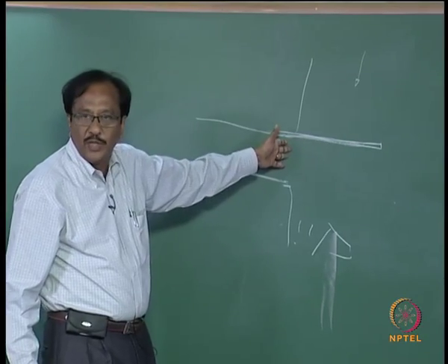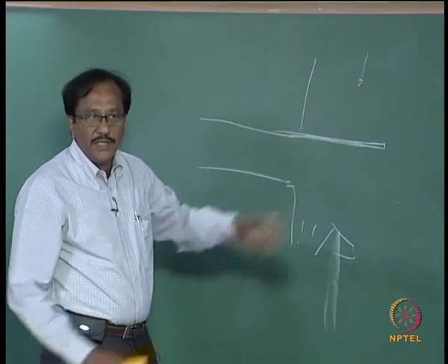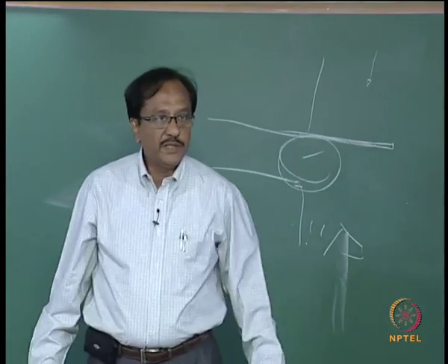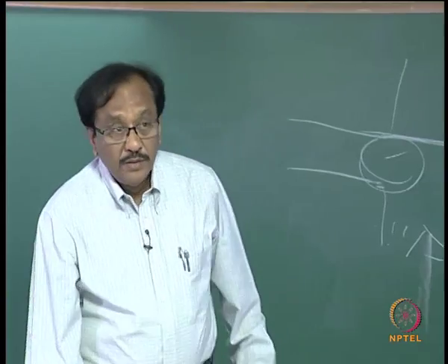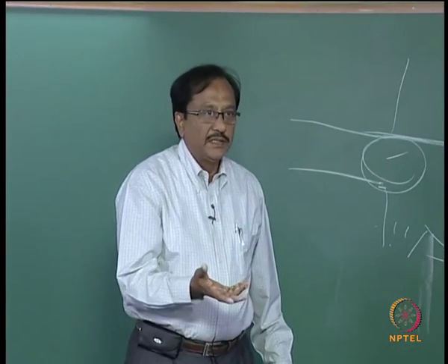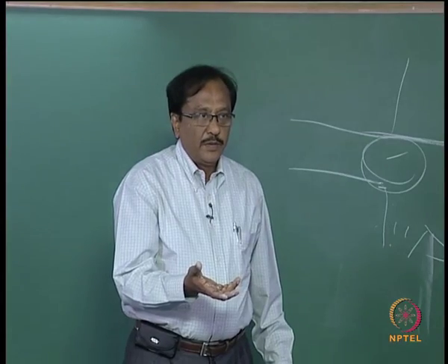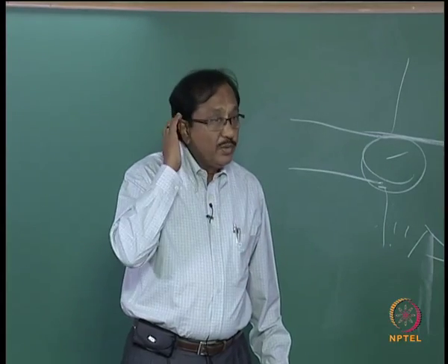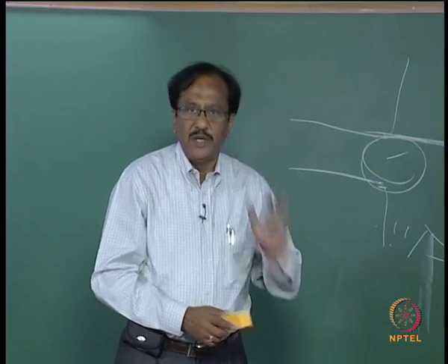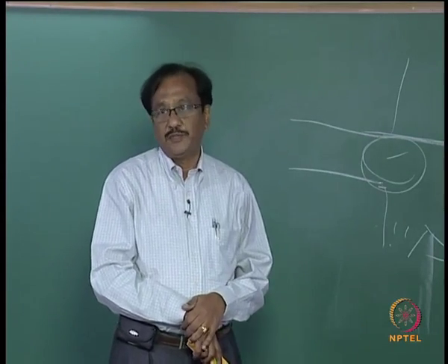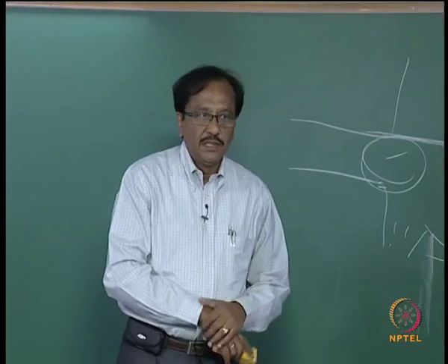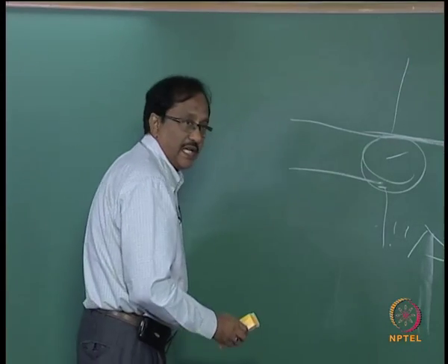Your solution is going to aggravate the problem. So you are going to have more sand deposited. So although the solution is not so difficult, it is a bit tricky because you need to have, most important, the knowledge of the sediment transport, particularly its direction apart from your quantity. Is that clear?